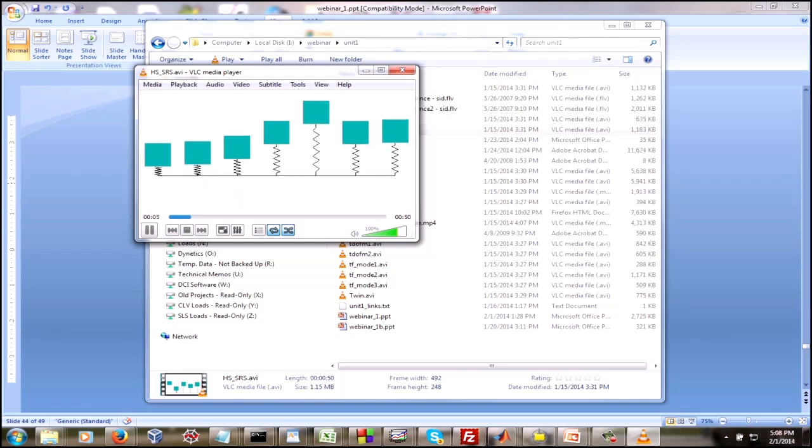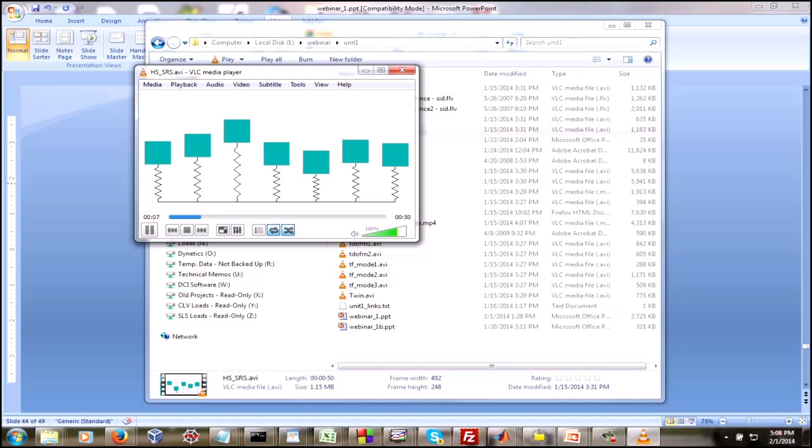There's also components we've kind of talked about earlier, like inertial navigation systems that have their own control algorithm, maybe a servo mechanism of some sort. And the vendor of these components may be assuming that they're hard mounted. So if we take such a component, could be an inertial navigation system or even a hard drive, and we want to mount it via isolators, we need to make sure that it's not going to interfere with any control algorithm or cause any instability. So we need to check that over with the vendor.